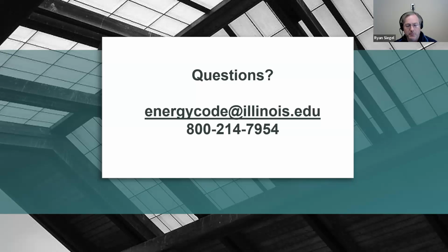And I did see a question or two come in regarding decorative fireplaces when we were talking about sunrooms and fireplaces. Part of this is, is the fireplace capable of providing conditioning to the space? So a purely decorative fireplace, for example, in my house, I have a fireplace with no chimney. That would be a purely decorative fireplace that has a little display of a fire on it. So that would be purely decorative and would not make a space conditioned.